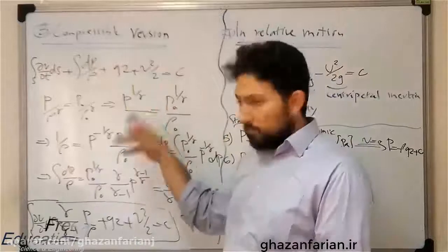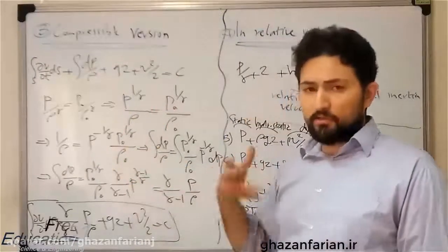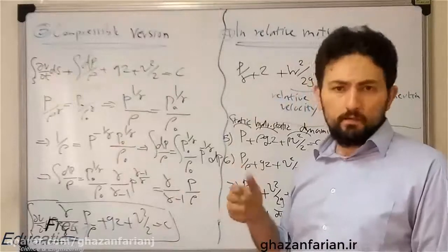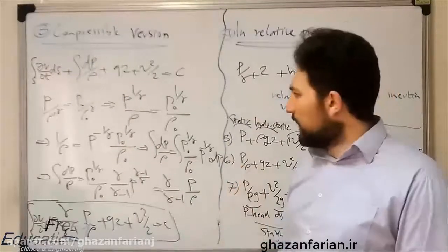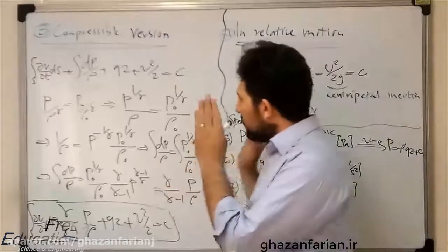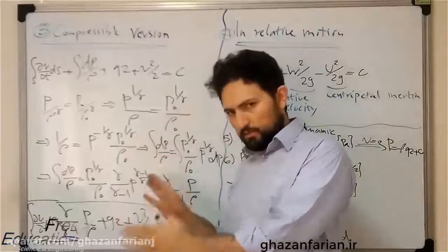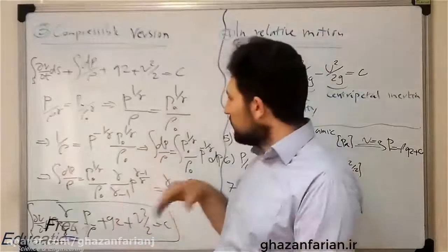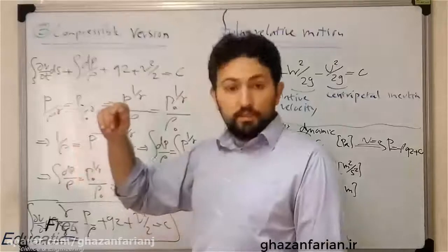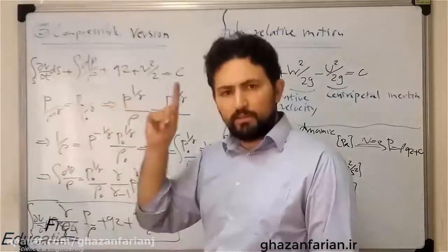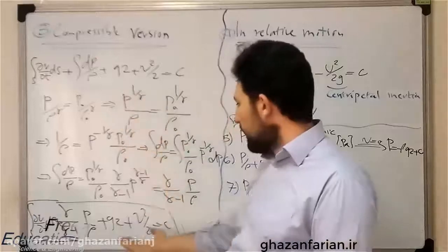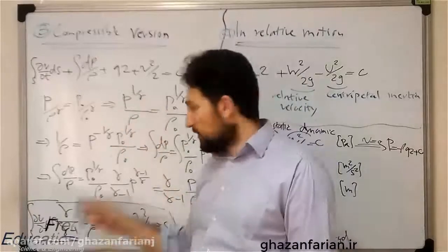Because the flow is inviscid, irreversibilities coming from viscosity vanish, and we also don't have heat transfer because we are writing the conservation of momentum, not conservation of energy. So the process is adiabatic, reversible, and consequently isentropic.